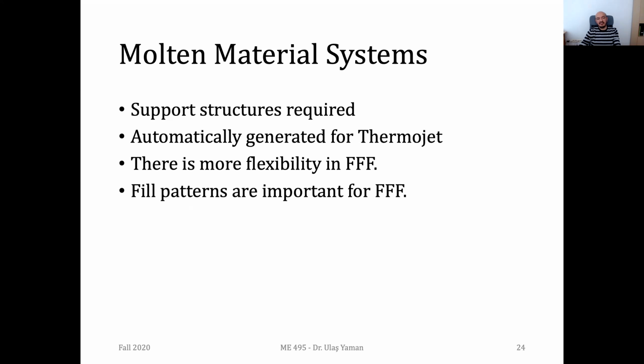And here, the fill patterns, the interior fill patterns, are much more important. And in the setting step of the fabrication pipeline, you need to spend more time on selecting the appropriate patterns for your part.